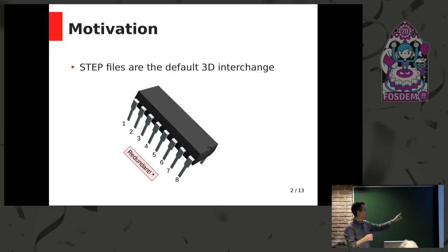That fashion is: I have pin 1, and I'm going to start by creating the origin, and then I'm going to create a vector from that origin, and now I can extrude along that vector. Oh, I need to extrude again in the same direction. Well, I start with another origin, and then I create another vector, and then I extrude along it. So you have this repeated function throughout the file. It's a very safe way of generating.